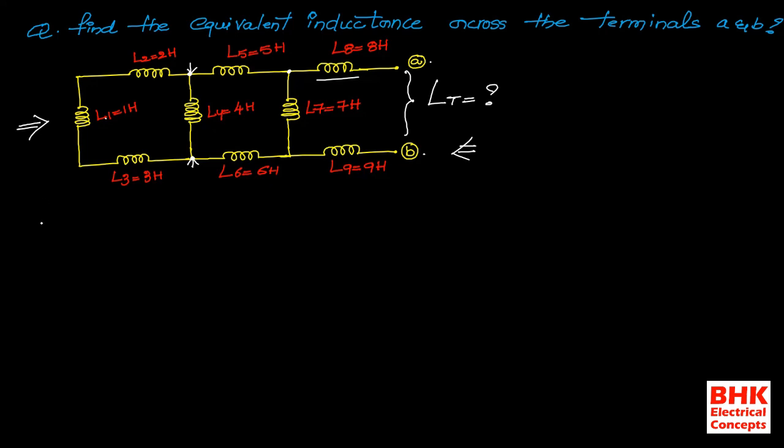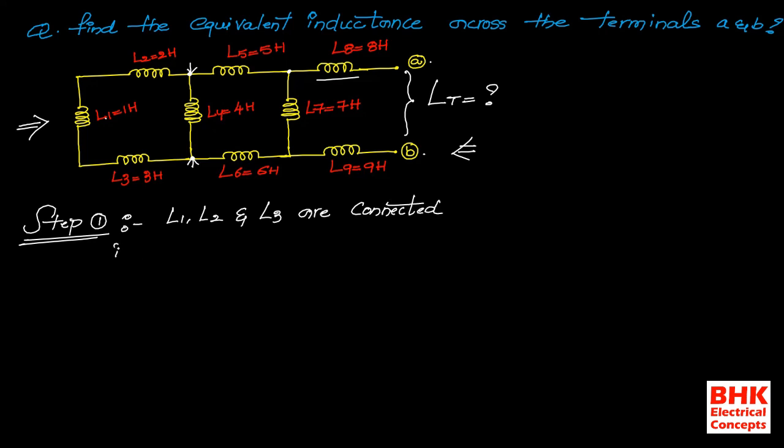Now see here, step number 1. L1, L2 and L3 inductances are connected in series. When inductances are connected in series, to find the equivalent we can directly add all the values connected in series.